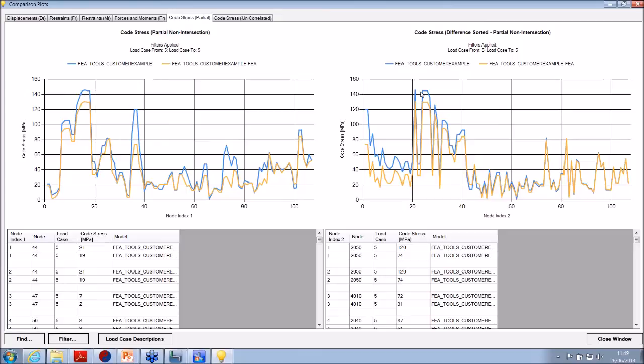And also things like Tony mentioned, the torsional intensification factors, which currently are 1 in B31.3. If we include an accurate torsional intensification factor, then that could also cause things to not necessarily work in your favor. But I think you would still want to know, even if things weren't working in your favor, if you have an increase in stress or force or moment or something with the more accurate data.